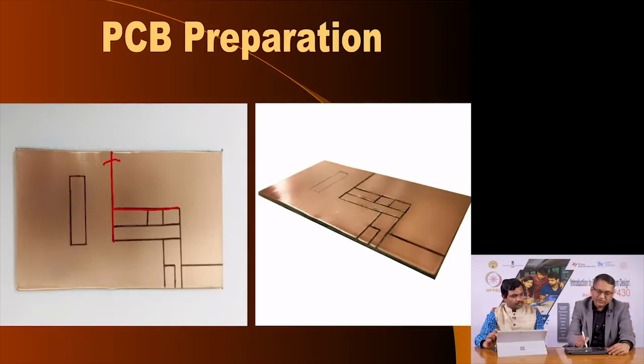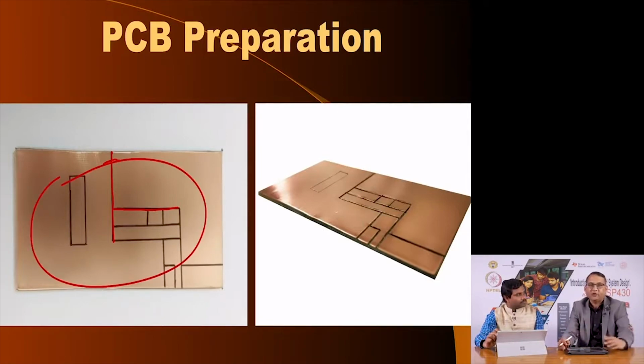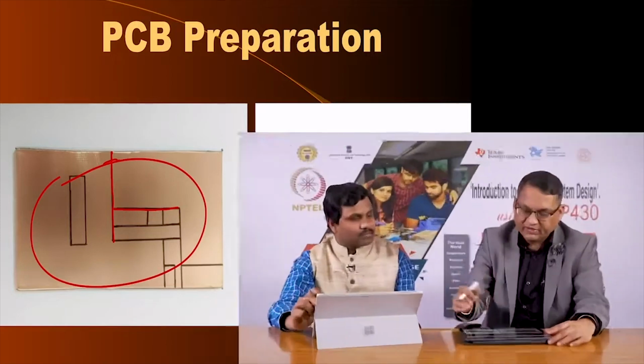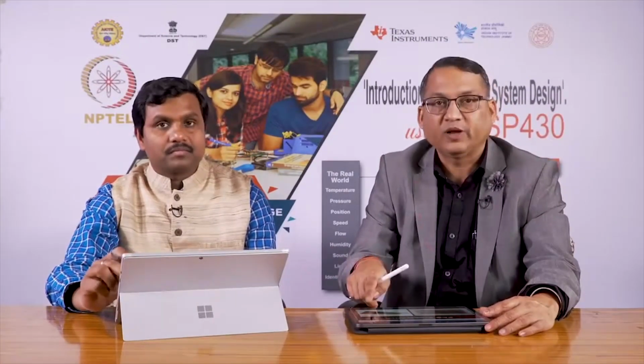So, you could utilize one side for soldering your circuit, and the other side of the copper could be connected to ground to create what is called a ground plane, and having a ground plane is very helpful whenever you are testing and prototyping high frequency circuits. In fact, this is very popular with the ham radio community who build radio circuits of very high frequencies. This is a very popular, quick method of creating your own circuit implementation.